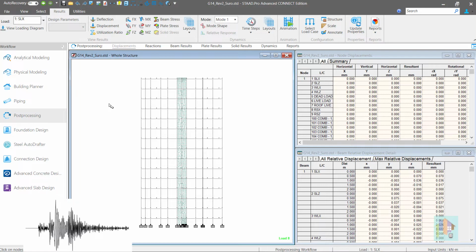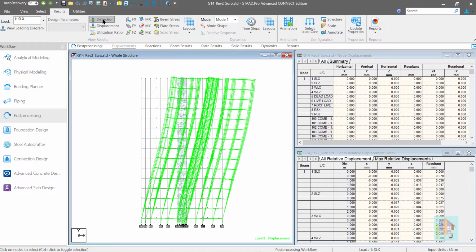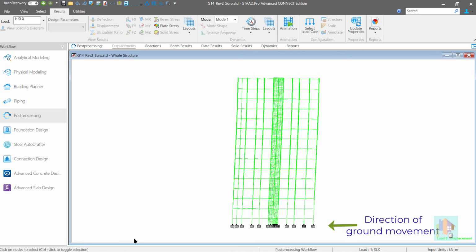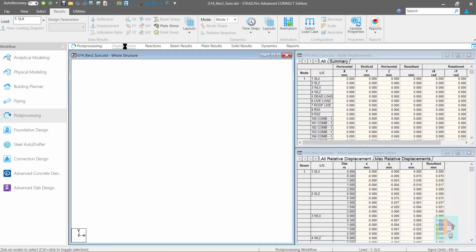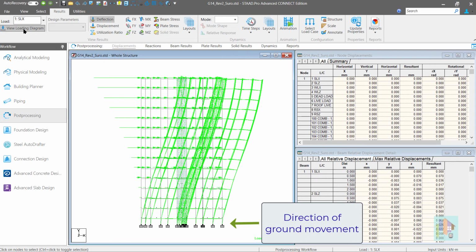Due to seismic activity, there are some disturbance in the ground in the form of waves, and due to this ground shaking, static condition of the structure is changed. As base of the structure is connected to the ground, it starts to move in the direction of earthquake. Obviously, this depends on the soil structure interaction, but rest of the structure remains static. If we consider the displaced shape of the structure subjected to an earthquake, it seems like a variable horizontal force is applied on it in the opposite direction.